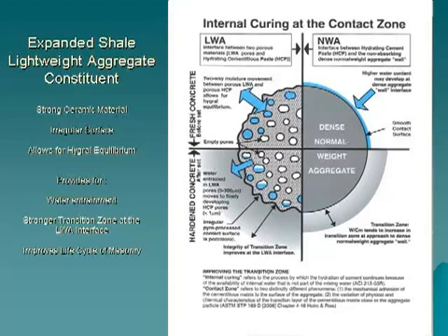It actually counteracts cement's shrinkage characteristics by improving strength through internal curing. Test reports show that properly manufactured lightweight block using expanded shale lightweight aggregate and good manufacturing methods yield high-performing lightweight concrete masonry units, resulting in quality lightweight masonry walls.